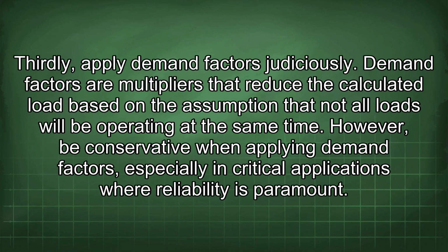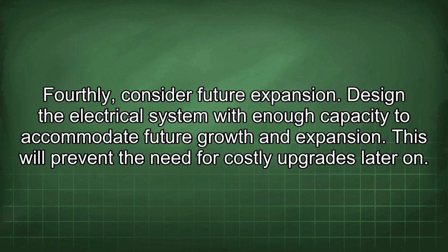Thirdly, apply demand factors judiciously. Demand factors are multipliers that reduce the calculated load based on the assumption that not all loads will be operating at the same time. However, be conservative when applying demand factors, especially in critical applications where reliability is paramount. Fourthly, consider future expansion. Design the electrical system with enough capacity to accommodate future growth and expansion. This will prevent the need for costly upgrades later on.